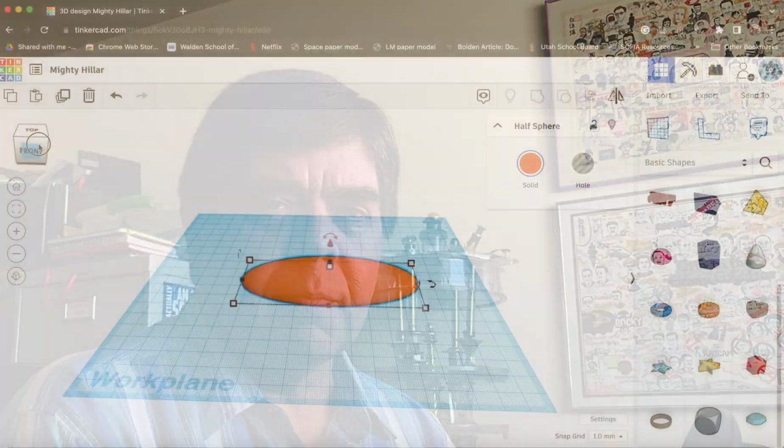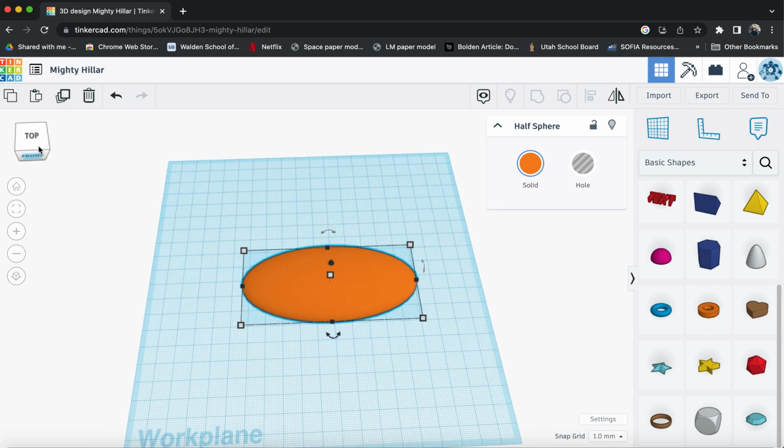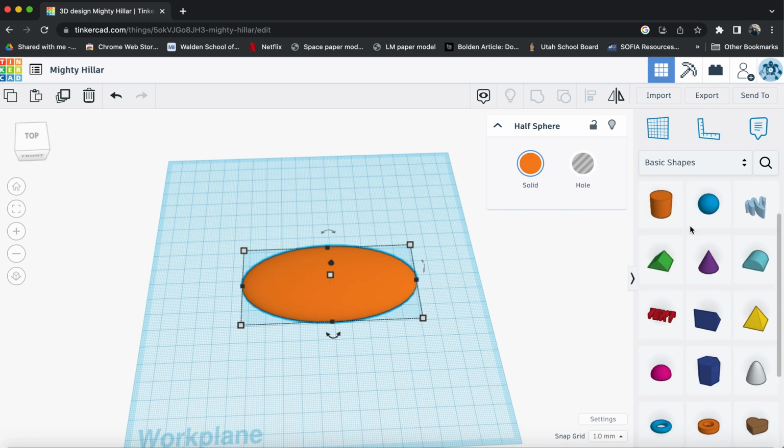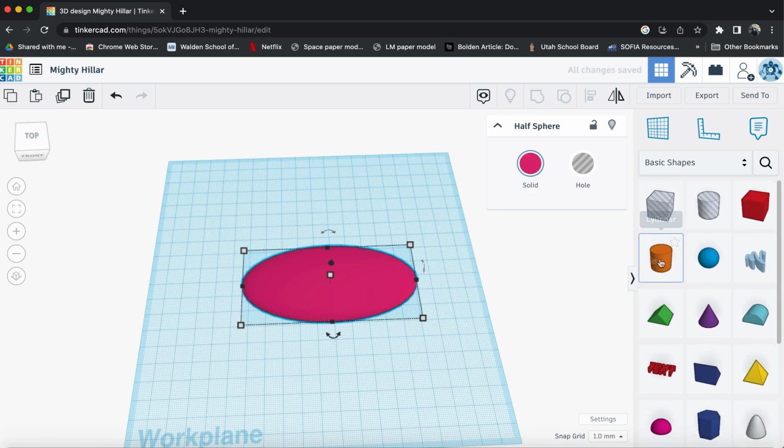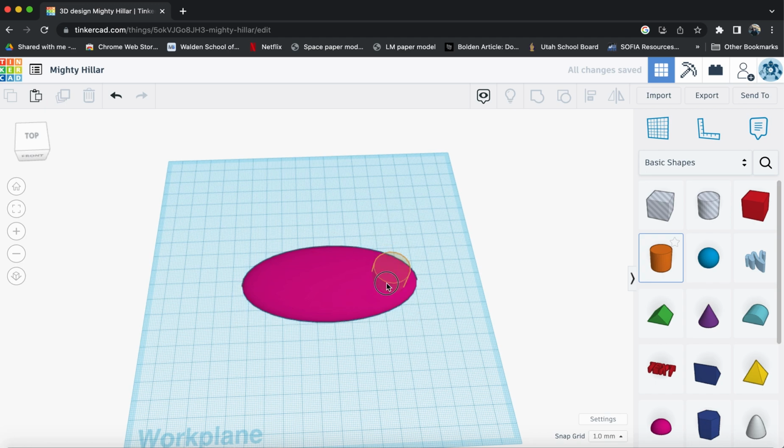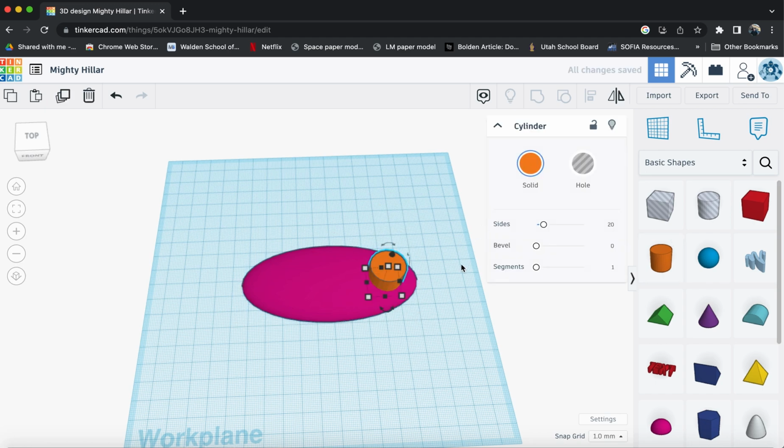We'll begin by drilling a hole through our keychain fob using a Boolean command. The hole is going to be basically a circular hole cut down through it, so the shape to do that is going to be a cylinder. Let's scroll down here. Here's the cylinder object. Then let's drag the cylinder onto the scene. That's about where I want to put the hole, but this cylinder is too large. If I point to the corner here, I can hold down Shift and keep all the proportions until I get this about the size of hole that I want.